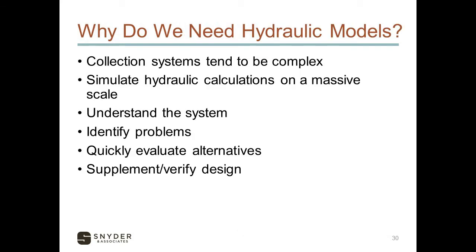Why do we need hydraulic models? Collection systems are complex. If you're in a larger community, you have gates, you have bypasses, you have a large sewer shed area with a large amount of flow and miles of sewer pipe. If we had to do that all by hand, it would be almost unachievable. We're able to build a network and simulate hydraulic calculations on a massive scale at a click of a button and have a computer aided process with that for our basis.